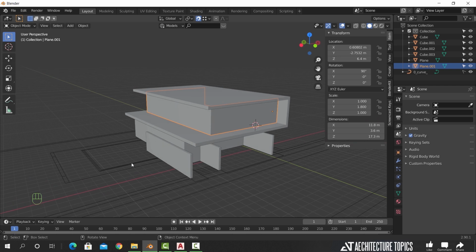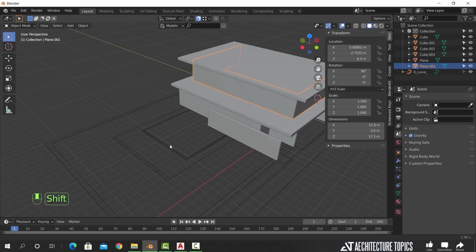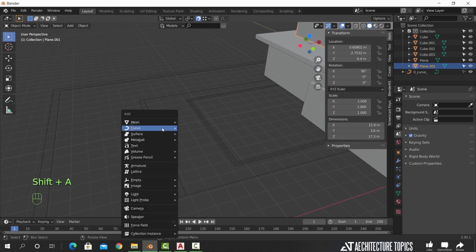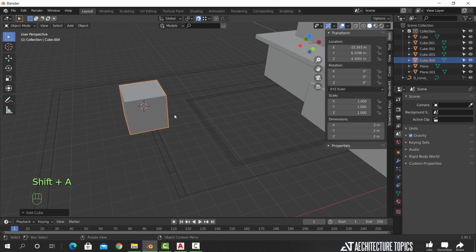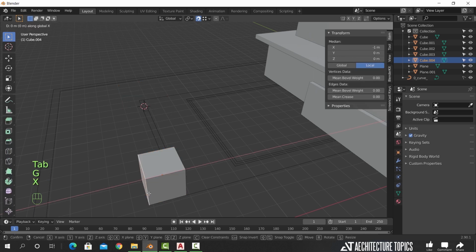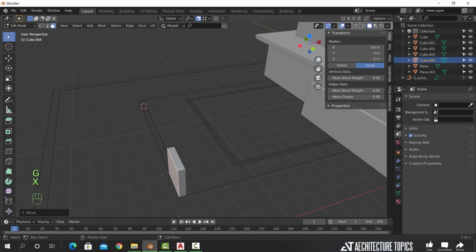Here to the left, we have a secondary mesh. We won't make any windows in this area, so I will make it from a cube. Add one here, and snap it to this corner. Inside Edit mode, switch to Face selection to match it with the drawing.